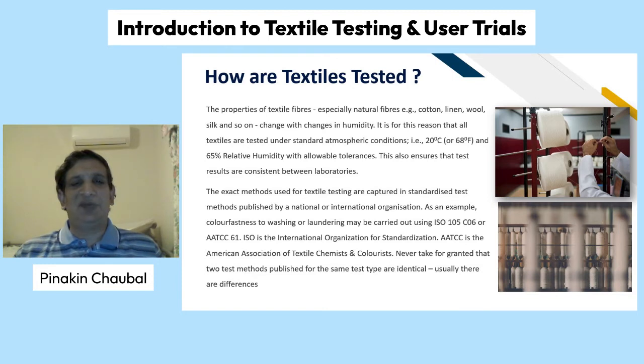The exact methods used for textile testing are captured in standardized test methods published by a national or international organization. As an example, the color fastness to washing or laundering may be carried out using ISO 105 C06 or AATCC 61. ISO is the International Organization for Standardization. AATCC, or A squared TC squared, is the American Association of Textile Chemists and Colorists. Never take for granted that two test methods published for the same test type are identical. Usually there are differences.